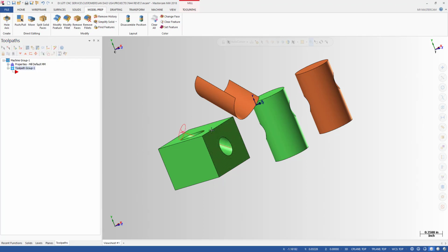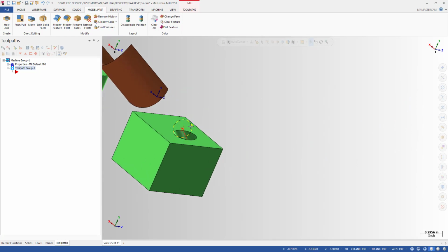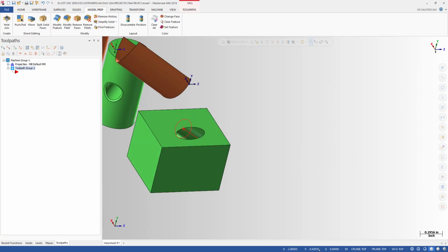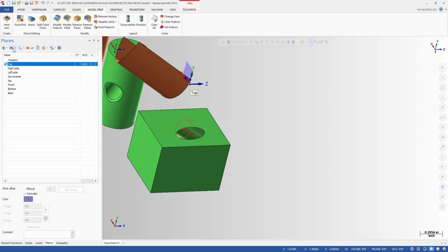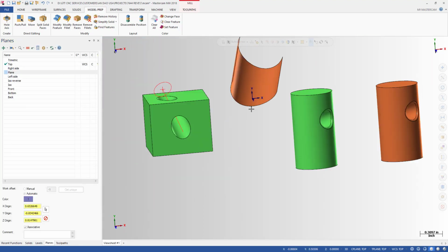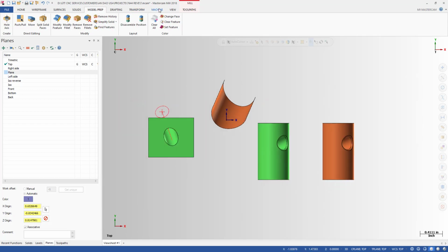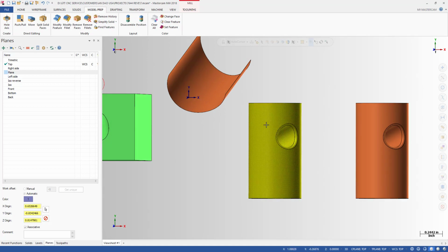Very simple. So you got the hole center line and the hole circle here, so you can create a plane here, a tool plane here for creating the tool path like this from geometry. Bing! Yes, and you can easily create a plane for making this hole. Yeah, very simple. And this is the case for solid. We just use the model prep and hole axis function.